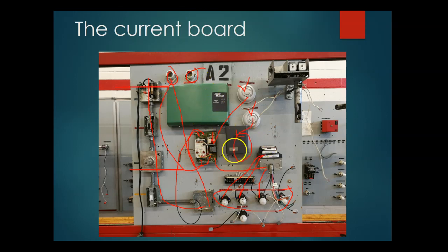I don't want to get that really messy, but again, this is your relay switch. You'll see how it connects once you start connecting it. You might be overwhelmed with the amount of neutral wires available, so this connector or hub over there is to connect all the neutrals together. If you see, they connect vertically, and each line is neutral. You see why the loop is here, because it's a neutral jumping from one to another. So you can connect one neutral here, and all of them are going to be neutral, so you can plug all the neutrals back into it.